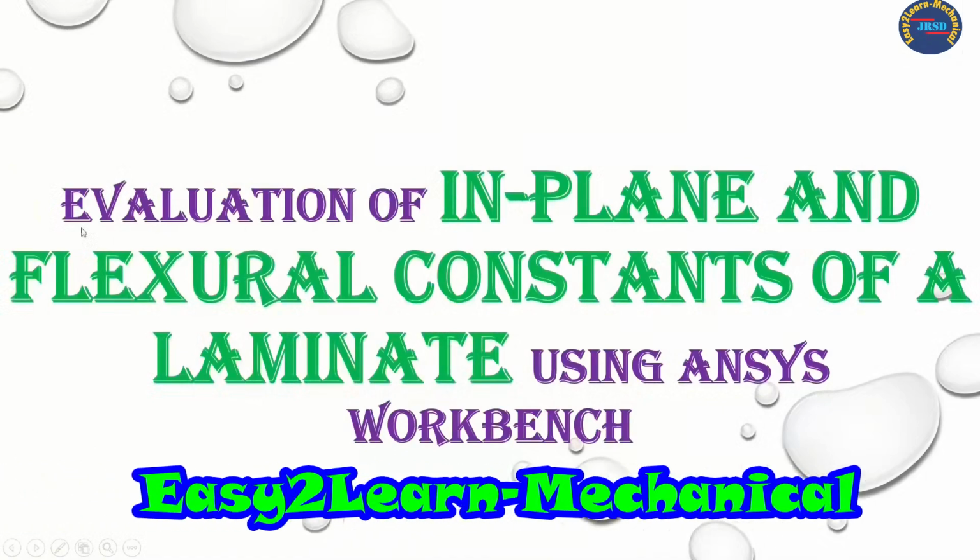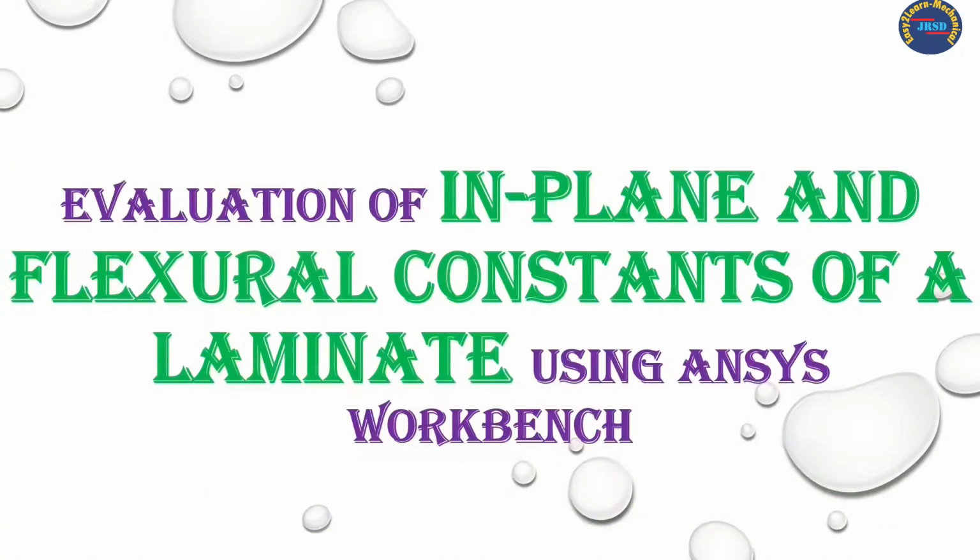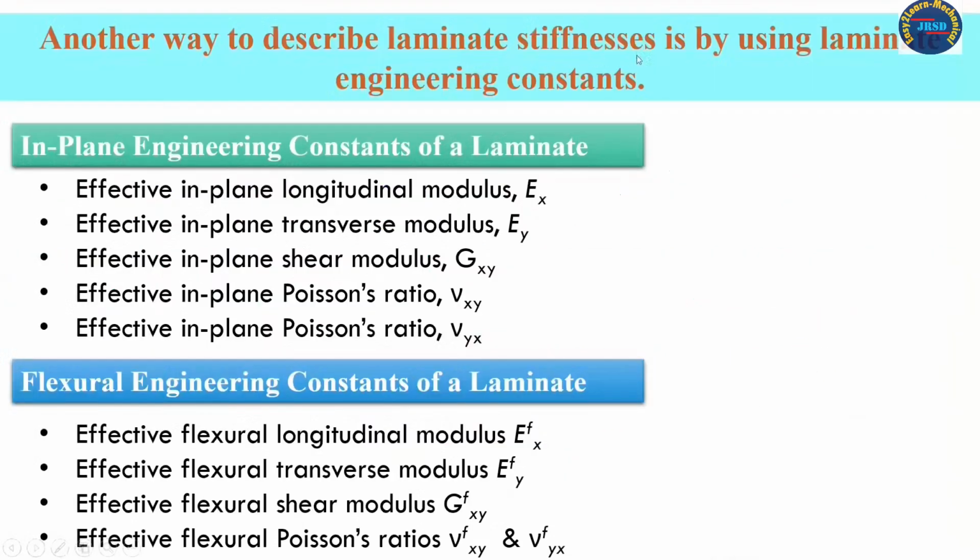Hi friends, in this video I am going to explain the evaluation of in-plane and flexural constants of a laminate using ANSYS Workbench. The laminate stiffness can be defined by using the laminate engineering constants. So the in-plane engineering constants of a laminate are nothing but the effective in-plane longitudinal modulus, effective in-plane transverse modulus, effective in-plane shear modulus, effective in-plane Poisson's ratio.